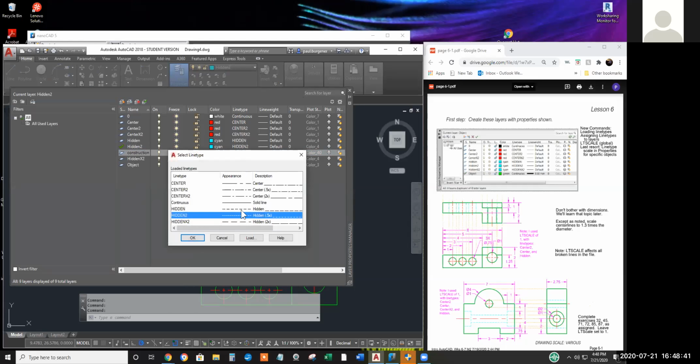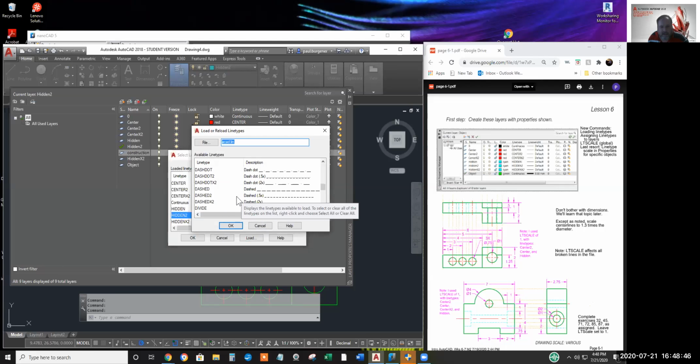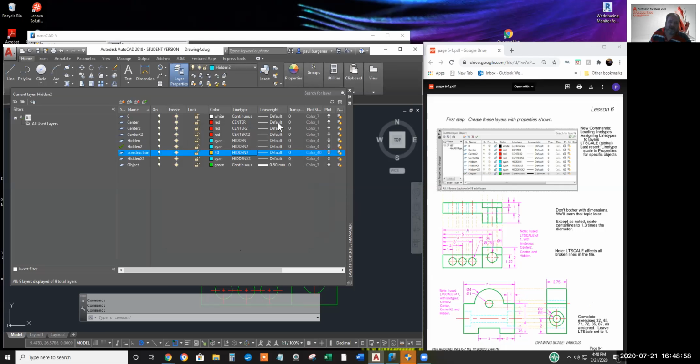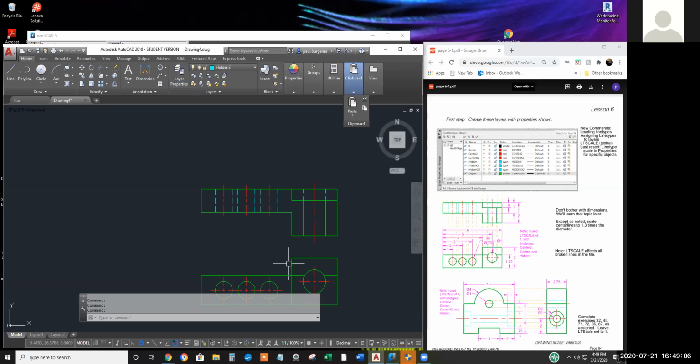And I probably used a unique layer. I think there's a dot layer. Yeah, I probably used one of these dot flavors. And that way, by putting all my chalk lines on a unique layer, I can simply freeze the chalk line layer rather than trim away.